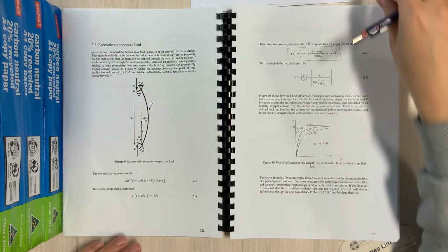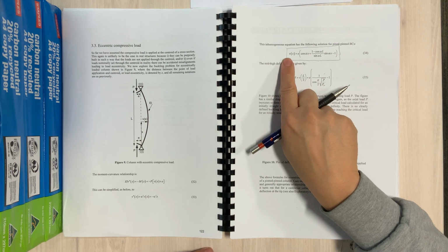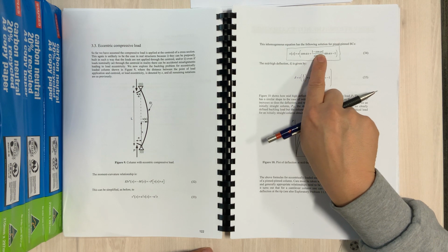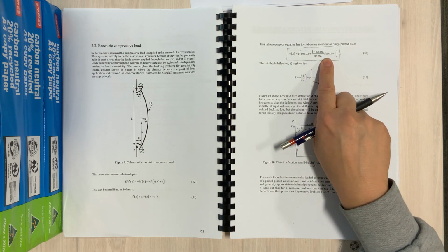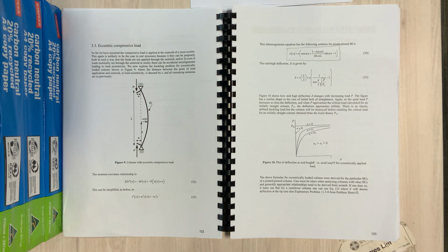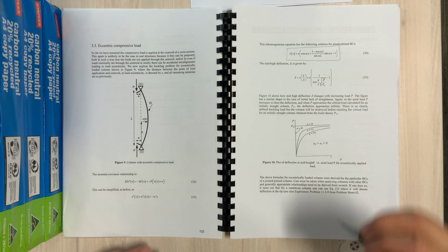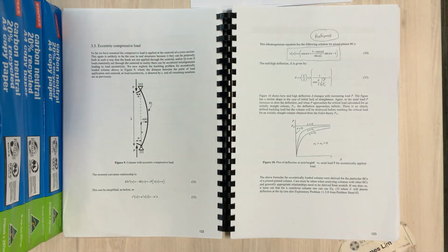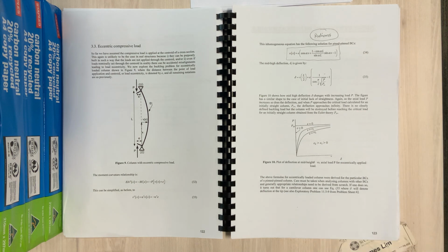Okay. So hopefully you can accept that the equation is of this form. v(x) is equal to eccentricity times cos(alpha x) plus (1 minus cos(alpha L)) over sin(alpha L) times sin(alpha x), minus 1. Just to remind you, we are of course dealing with radians. Sometimes in the past, when students have put some numbers through these calculations and found that they're wrong, the reason was not an error, they were just using degrees in their calculators. You should always be using radians. So just bear that in mind.